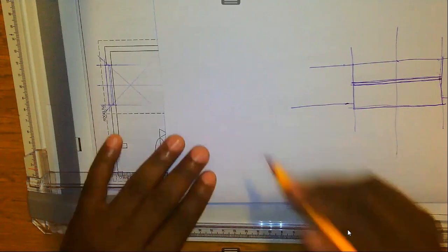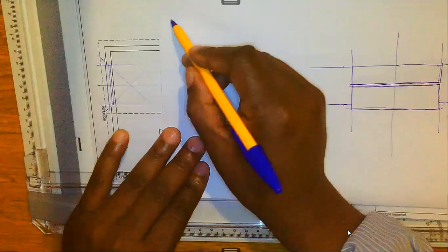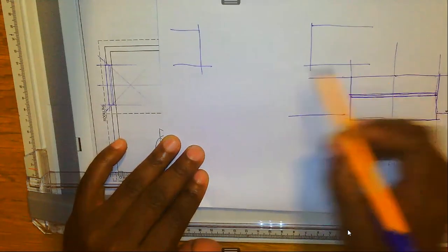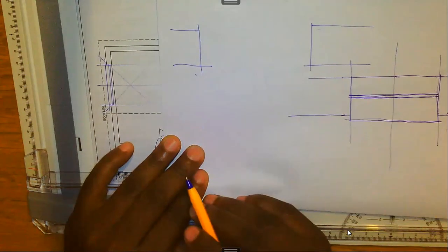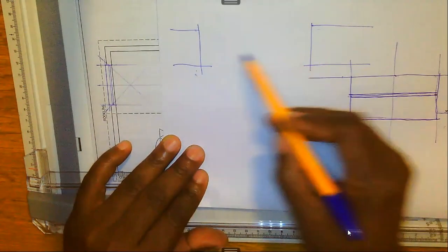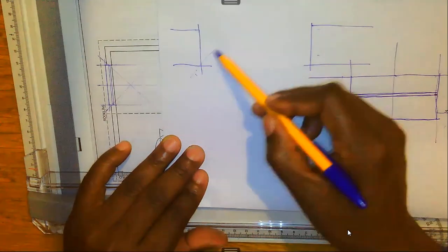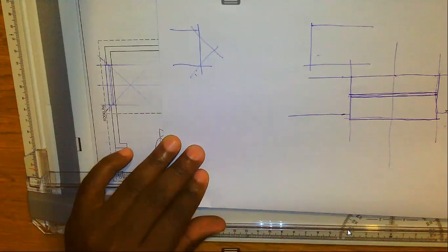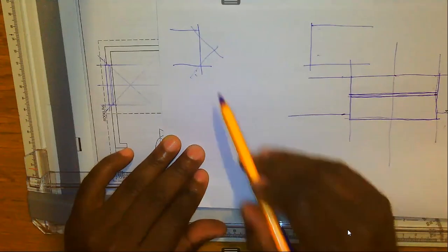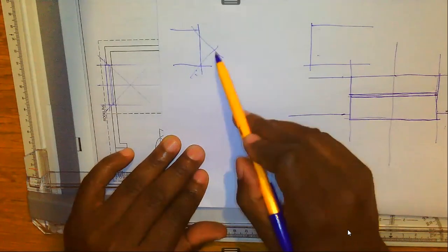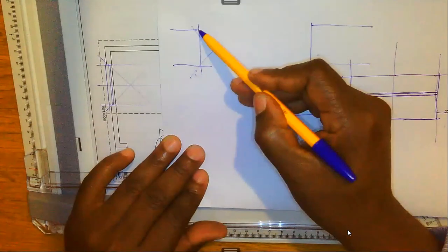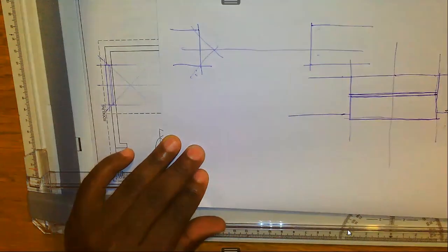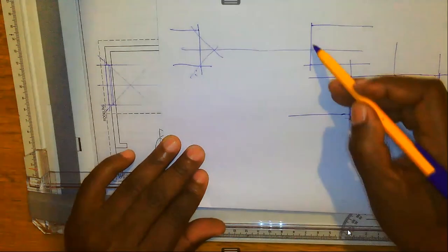Right, you have got the position of the wall. You have got, again, the position of the wall. This is the space which is in between. Right, we need a midline here, okay? So you miter there at 45 degrees. So every time you hear me say miter, I'm urging you to use a 45 degree set square, such that we don't need to measure from here to there or from here to there. We simply can draw like that. That is the line which is roughly in the middle.